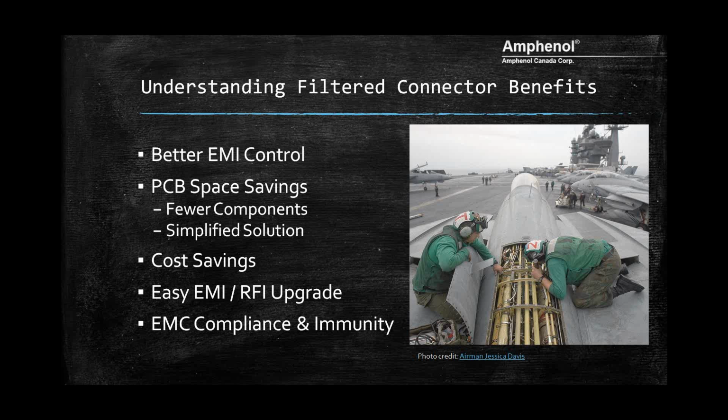Now, we're going to look at weighing out the differences between the two EMI type of solutions. So you have your discrete filter system where you design the components, circuit boards to filter out the noise, or you have a filter connector. So the thing is, with the discrete filter system, you'll have extra room in the enclosure that you need to accommodate for the printed circuit board. You need some proper grounding, springs, or coils to kind of ground out the board and your system.